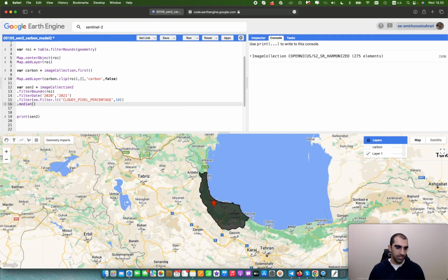That's why we must multiply multispectral bands by the scale factor suggested by the data description. It is very important to apply the suggested scale and offset values on satellite data before further processing, because it allows you to convert your data to the original range of values that should be used for the further analysis. So now we will have one mosaic cloud-free Sentinel-2 image.